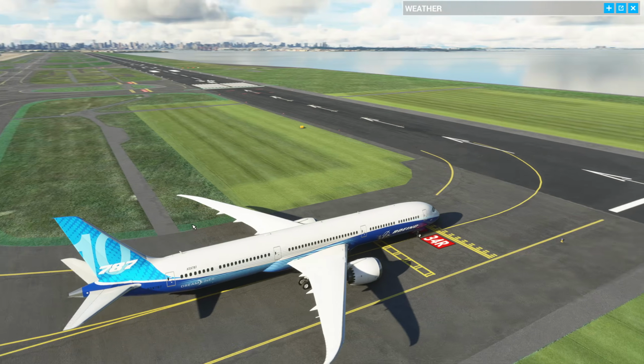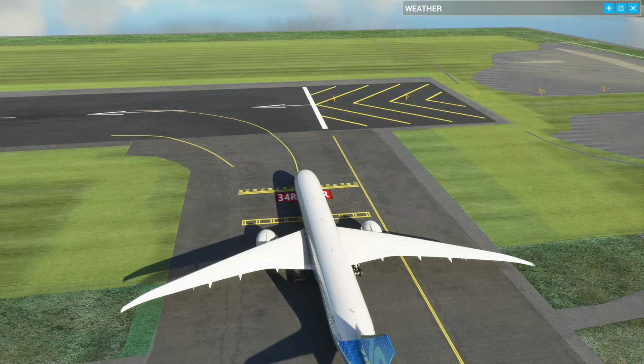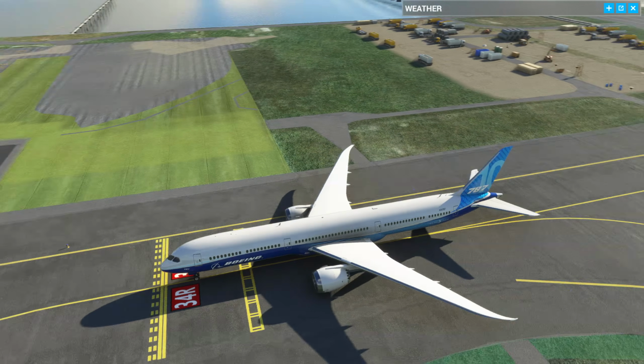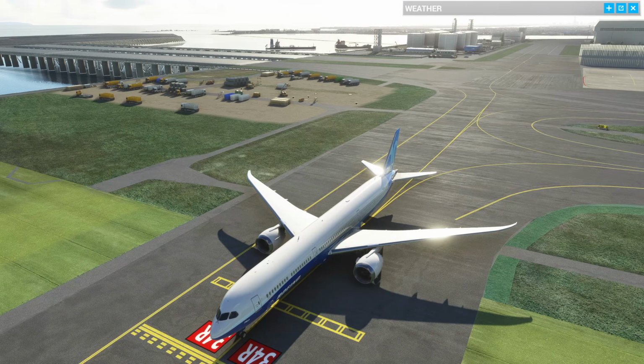So what do I mean by that? Well, if you think about it, as we're rolling on the runway, we rely on airflow over the controls to keep the aeroplane pointing where we want it to. Now, if this engine fails here, then we're going to have all the thrust on this engine, so we're going to be using the rudder to keep the aeroplane straight. If at the wrong moment, at a slower speed, like the 166 knots, with this engine failed, we went to full power on this engine, that's a lot of additional asymmetric thrust, and the rudder might not be enough to keep us straight on the runway. So that's what we're talking about.